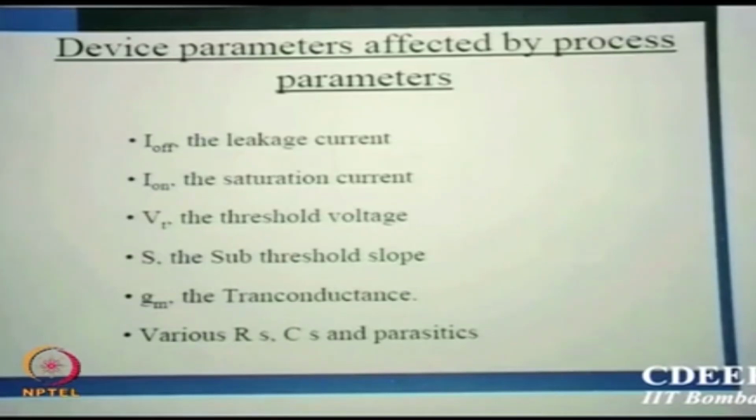Please remember our worry is on-chip variation, chip to chip variation, wafer to wafer variation, and run to run variation. Run means the 201st run, next the 200th run. So there is run to run variation. So huge problems, okay. We do everything fantastic, we say everything is controlled, and then we see all the variations.